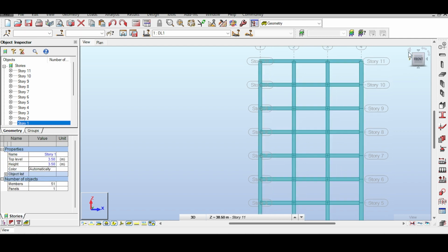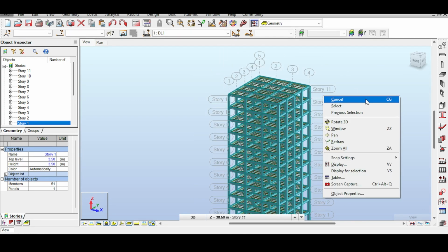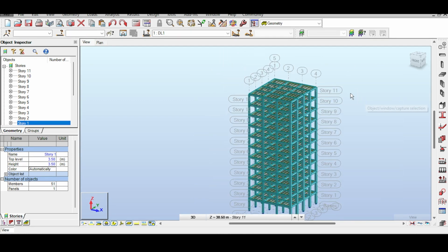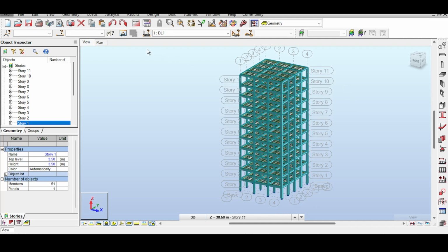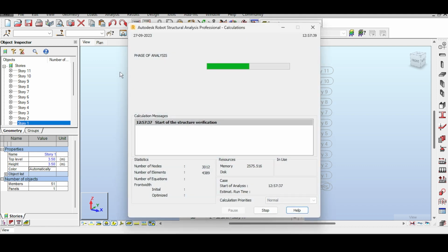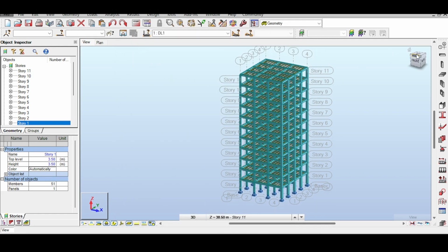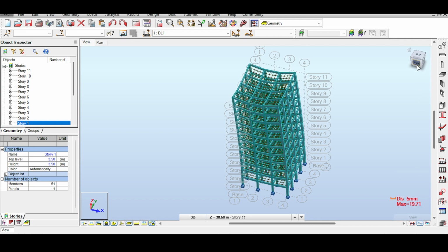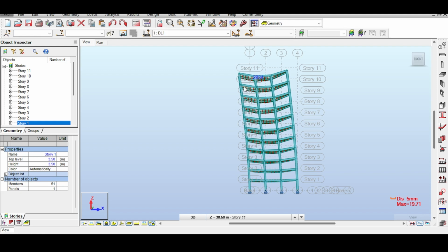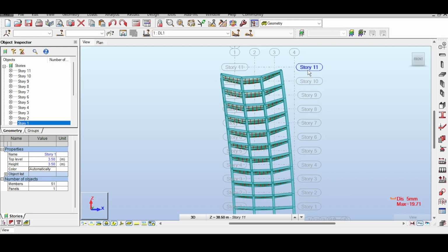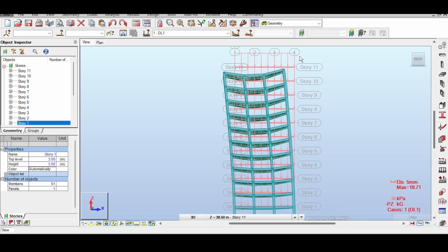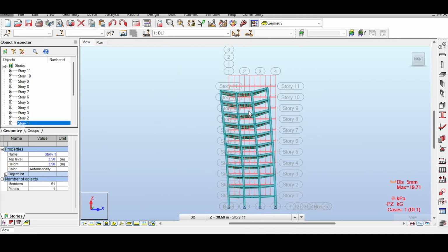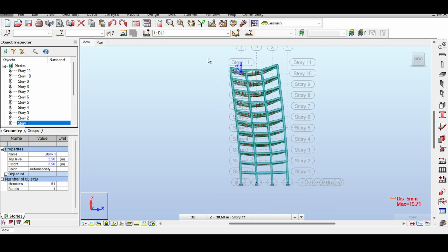So here is the thing now. Now you would think that, okay, it doesn't matter because I have vertical forces, and vertical forces should cause vertical displacements. No, that's not the case in this case, because our vertical load-carrying elements are not symmetric around the center of gravity of that slab. Let me run the calculation to show you. And there we go. So I've run the calculation, and now the moment of truth. If I open the deflection, you can see the tower leaning on the left side, which is amazing. Like there is no horizontal force. I swear, here are the forces. They are purely vertical, as you can see. Yet those vertical forces caused the tower to lean to the left.